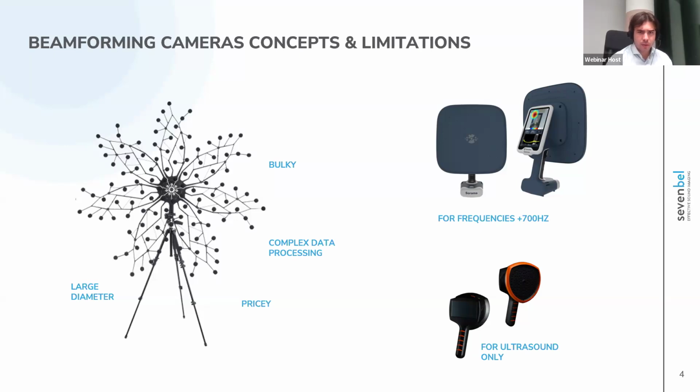So an acoustic camera, and this will be an extreme oversimplification, is an array of microphones which are placed in a measurement plane, in a so-called measurement surface. And we will assume that they all capture the same acoustical signals, except that they have phase differences, so that a certain sound front will arrive first to one side or the other of this array. By comparing the phase differences between the signals that we measure, we will be able to deduce an angle of arrival and the position of a source.